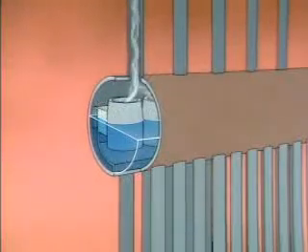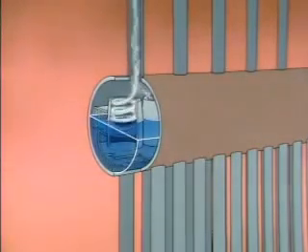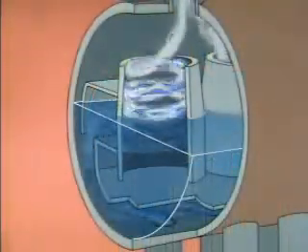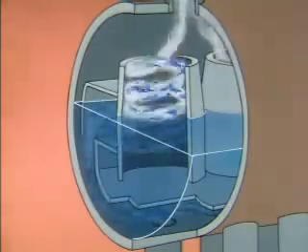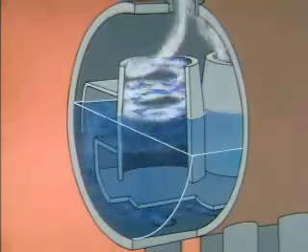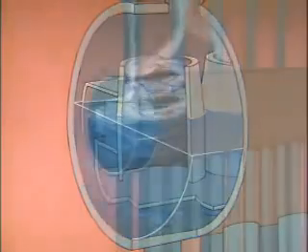One type of moisture separator is a centrifugal separator, or cyclone separator, located in the steam drum. It works by directing the steam-water mixture into a circular chamber. The circular shape of the chamber causes the mixture to swirl around. The swirling action creates a centrifugal force. This force flings moisture droplets against the chamber walls. Then the droplets run back into the drum. The lighter steam flows out the top of the chamber.